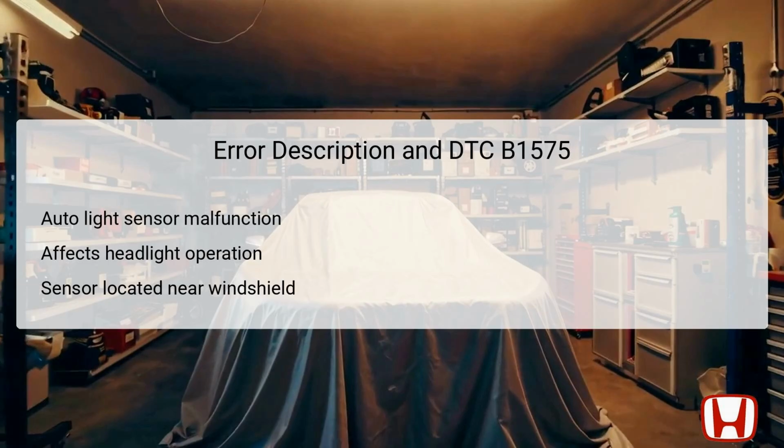When the sensor malfunction occurs, it could prevent the headlights from transitioning as needed, creating potential safety hazards. Regular inspection of this sensor is crucial in maintaining optimal headlight performance. Remember that effective troubleshooting involves checking the connections leading to the sensor and the sensor's performance itself.